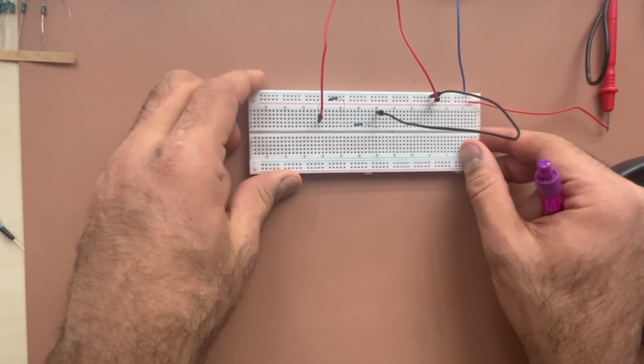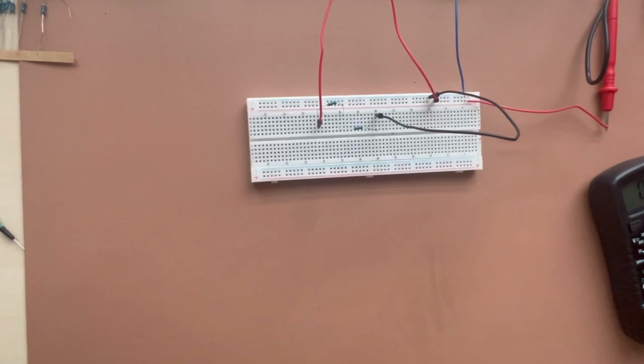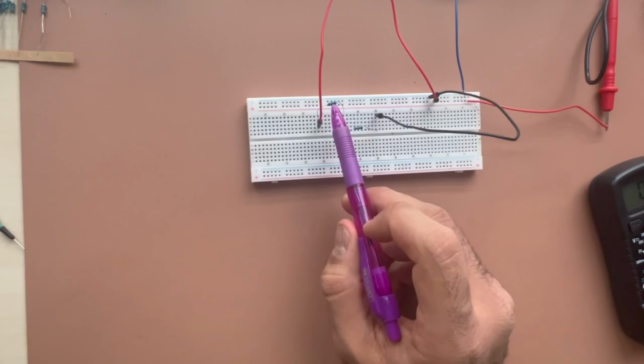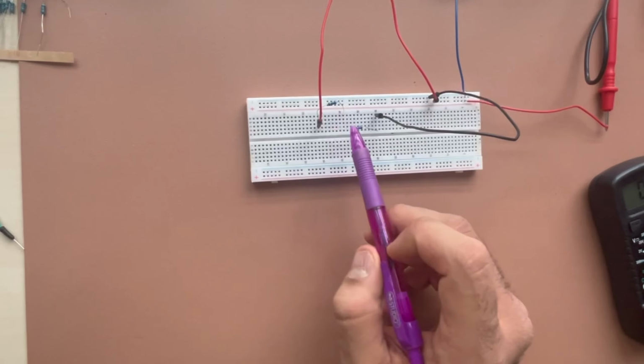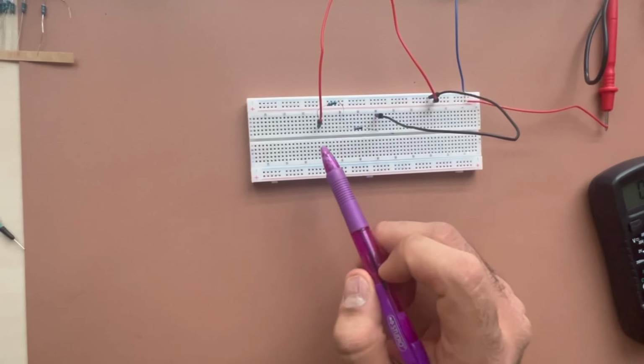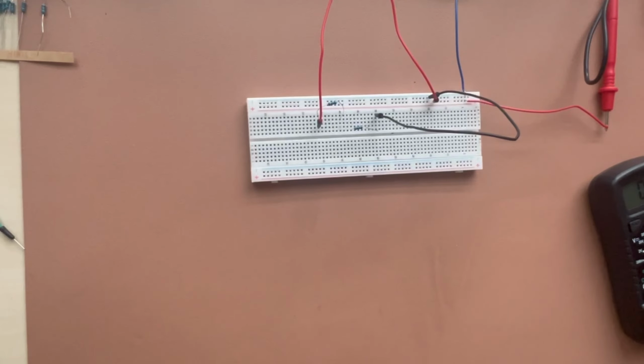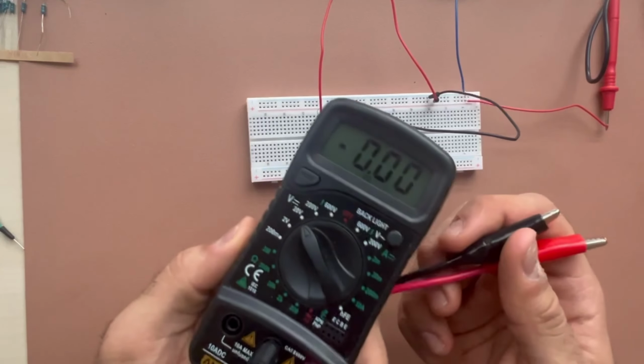And the question simply asks for a couple of things. The very first one is about the voltage. As we all know from the calculation, the V out, the voltage of this resistor, would be the resistance of this resistor divided by the total resistance times the voltage of the source itself. So simply, we can just use the voltmeter. It doesn't matter. Again, the voltmeter that I'm using is going to be like this.